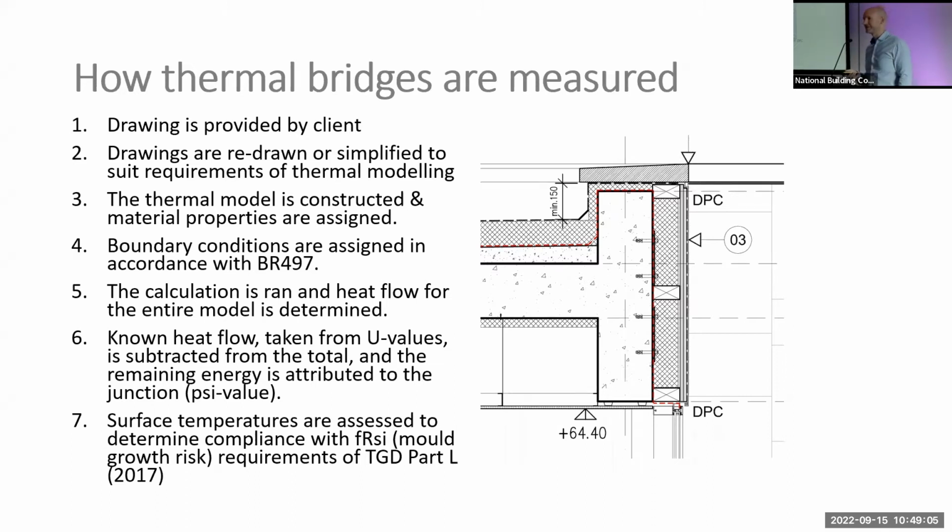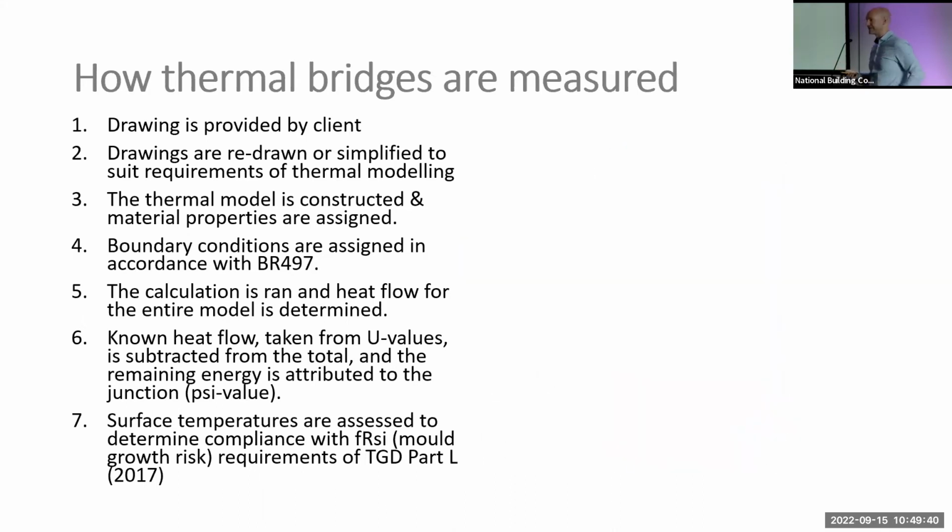Oftentimes, someone will say, can you carry out thermal bridge assessments on our window details? No problem. So they send over some window details, and you look at them, and it says insulation by others, thermal break by others. And you're going, okay, what is that? And how thick is the thermal break? We don't know. And then about 2 days later, you get sent a separate package, and it's the window supplier's package. And you open it, and the window is a completely different profile to what's in the other details you got. And it's sitting on an angle that's different to the one in the architectural drawing. And it's showing a pressed metal sill, and the other one is a concrete sill. So they're similar, but they're not the same at all.